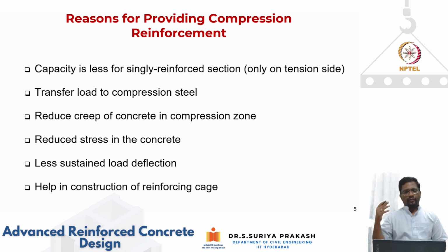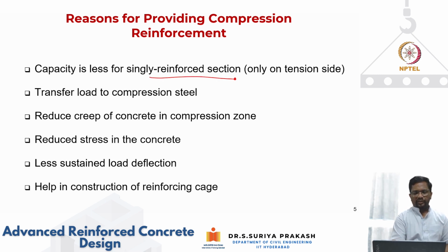So from a loading point of view, if the size of the section is limited, then in a singly reinforced section we cannot keep on increasing steel and get more moment resistance. We have seen that when the steel becomes more than the balanced reinforcement ratio, you don't get much more moment capacity. So that is another reason: we have to also put steel on the compression side to get more moment capacity.